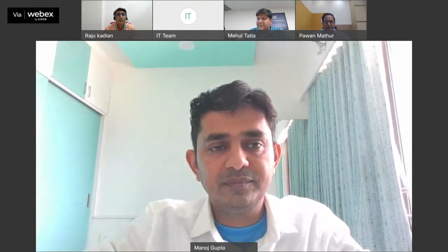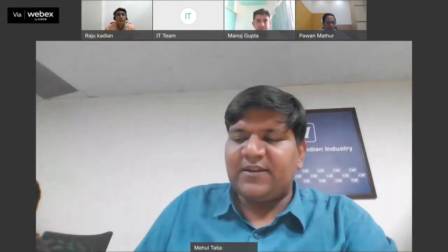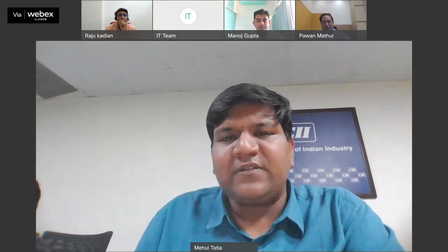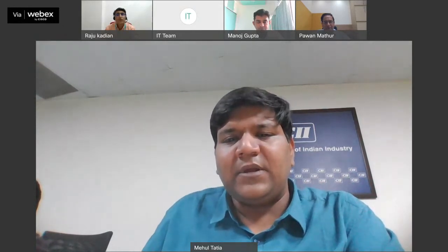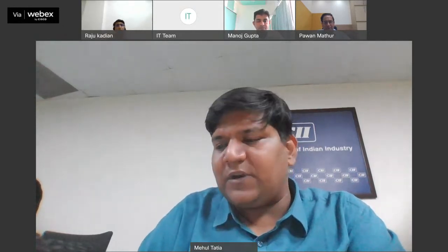Thank you, sir. So there's one more question for you. This is regarding centrifugal compressors. What are the minimum sizes available for centrifugal compressors, and at what specific energy levels? For screw, we know it is around 0.17 kilowatt per CFM. So what is the minimum size of centrifugal compressors and at what specific energy level?